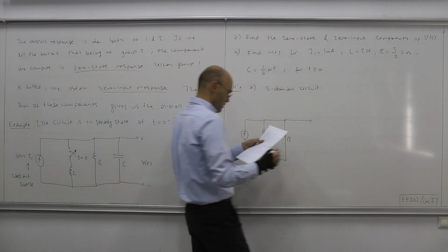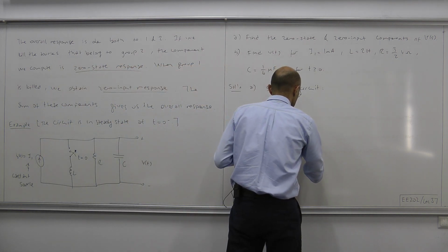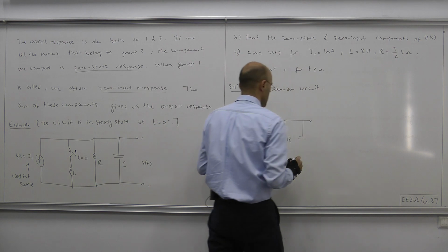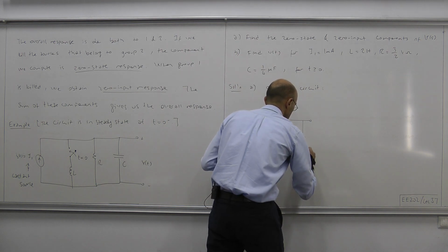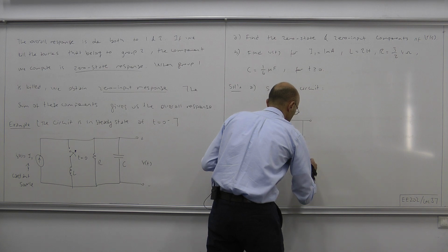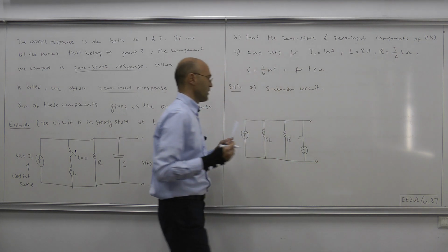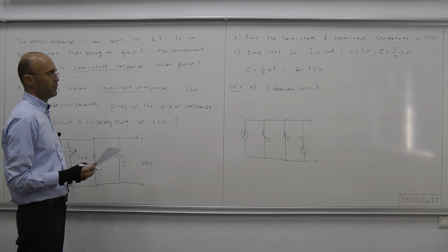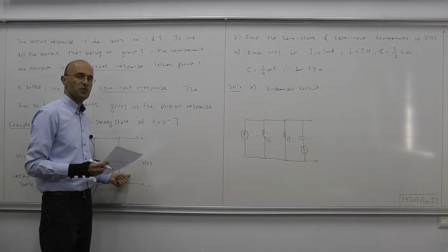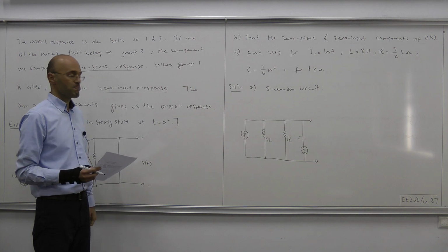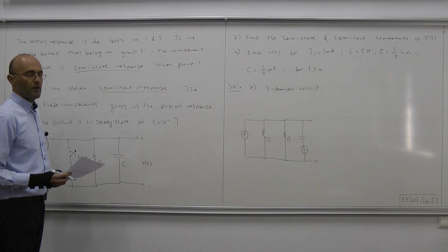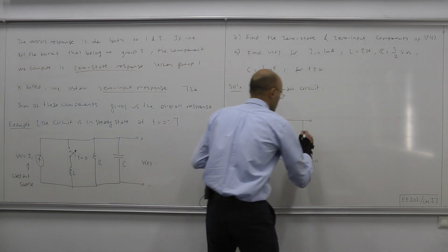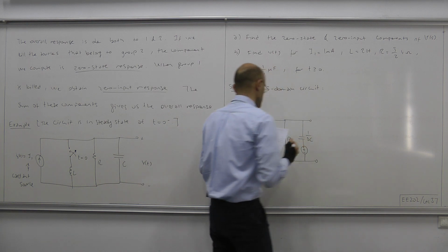So what we have therefore is, for the capacitor, the impedance of the capacitor and an independent voltage source, for instance, that would represent its initial condition, which is I1 times R. The impedance of the capacitor is 1/SC.